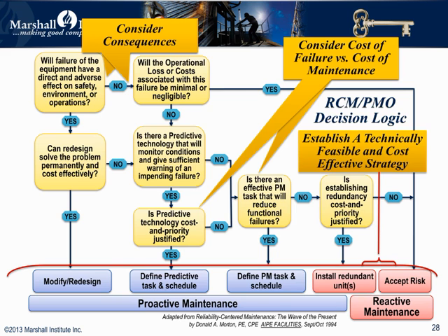A common feature and tool of RCM-based analysis is to provide a kind of decision tree to logically and consistently select the proper maintenance strategy for virtually any circumstance or context, based primarily on the consequence of loss, but fundamentally screens alternative strategies based on technical feasibility and economics. This logic tree is a useful example, but it's only one of perhaps hundreds of such logic diagrams available in the literature.